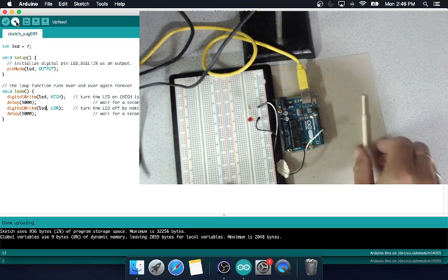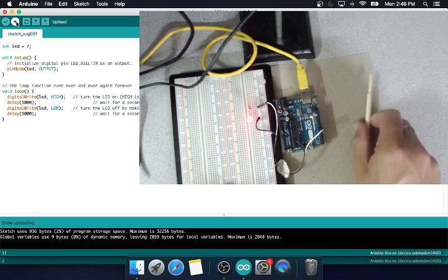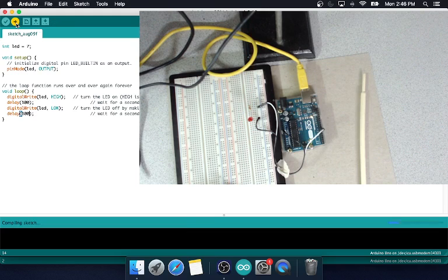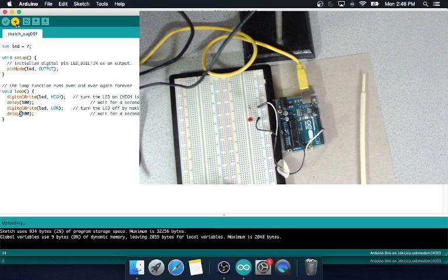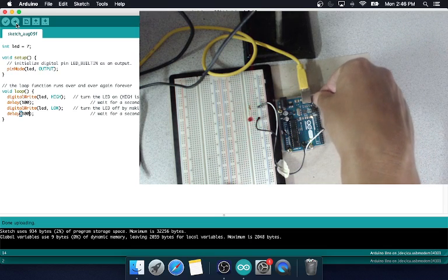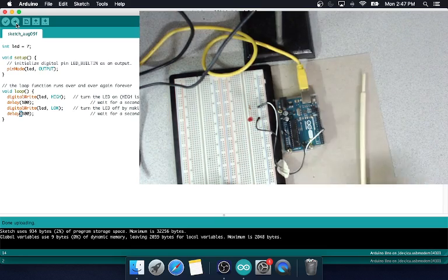And if you notice, this isn't blinking anymore. This stopped blinking because anytime you upload code, you overwrite the old code on there. So basically here I can set this to 100, upload this, and you should see the blink rate change quicker. And there's a reset button here. When I reset this, it's going to run this code again because whatever the last code is in it is going to run. There you go. It's running it.